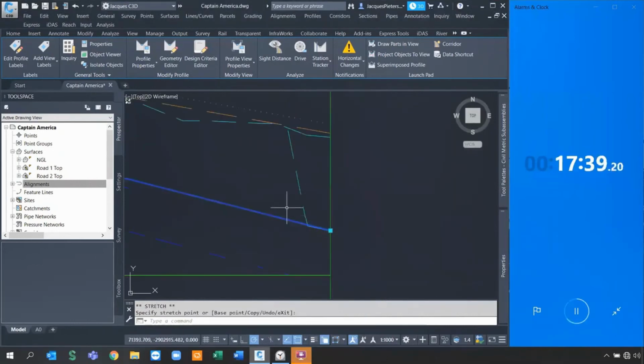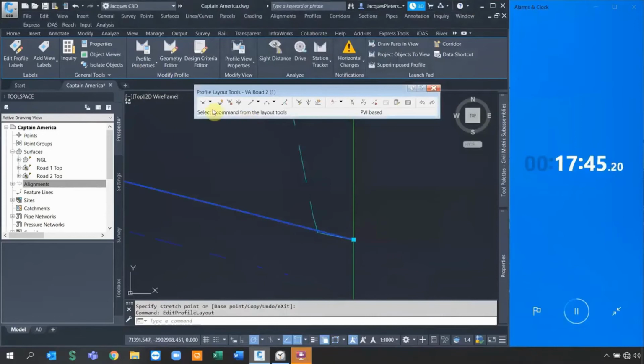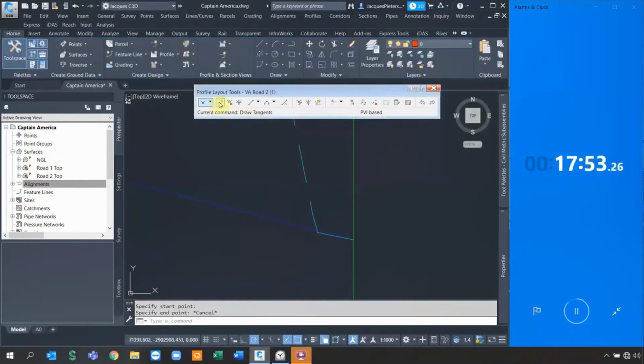So what I'm basically doing is tying the two roads to one another, so we don't have one road higher than the other. That's the main critical stage. And then I want to follow this line because it needs to tie in directly all the way to this ETW to the side. So I'm just going to insert the new PVI, and add it to the new PVI.